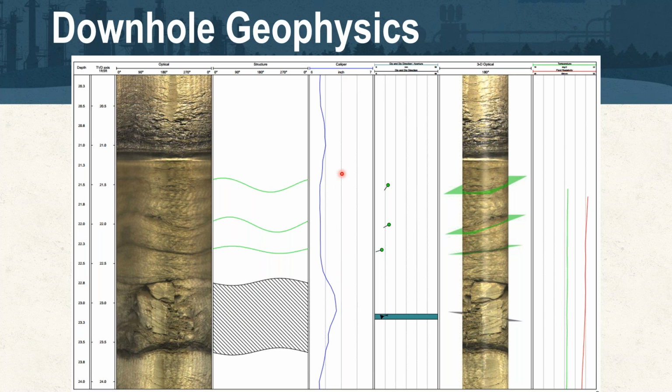And so again, coming into this idea of coming in with characterization and ultimately the remediation plan, we want to make sure that we're looking at every interval present. And with that discrete interval sampling tool, we can actually isolate these individual bedding planes and that higher K zone and actually look at the chemistry and the fluid properties of that specific area within the formation itself. Next slide, please.